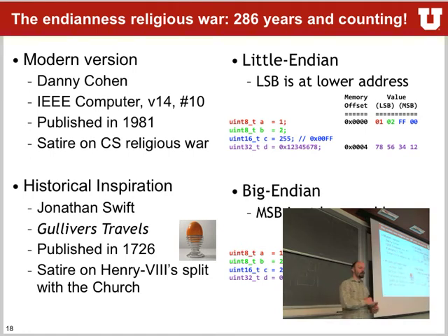ARM Cortex-M3s are by default Little Endian, but on many ARM systems you can switch at startup to Big Endian. There are also a couple of instructions in ARM assembly, more specifically REV and REV16, which will change a Little Endian to a Big Endian number. That's sometimes very useful if you communicate over a network and have to talk to somebody who is not Little Endian like you. You can use the REV function to flip it around in your instruction codes.